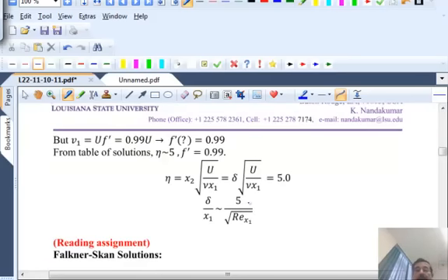Yeah, we already talked about this: how do I define the edge of the boundary layer thickness by simply asking the question, for what value of eta does f prime become 0.99? f prime is the ratio of v1 over u. Okay, f prime is the same as v1 over u. At what position of eta does that become 0.99? And you find that that is equal to 5 from the table.